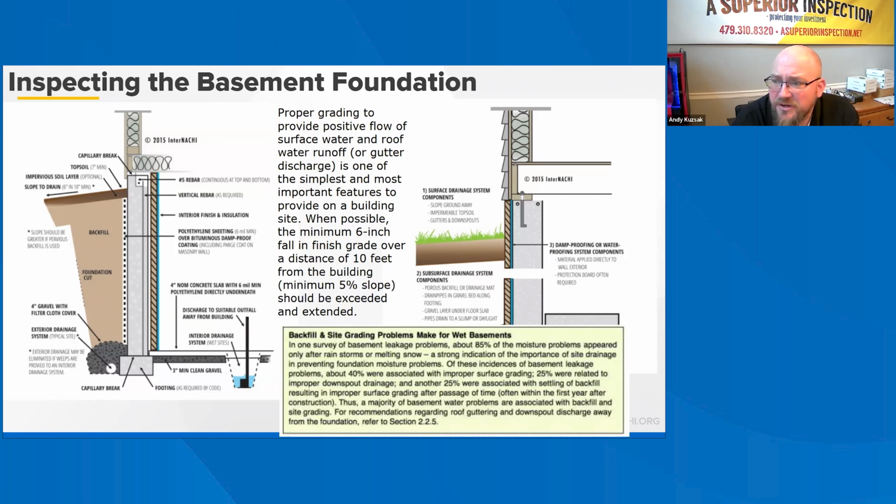Concrete and masonry construction will develop cracks due to shrinkage effects. These cracks widen over time, providing pathways for water intrusion. Controlling these cracks is important, even though cosmetic cracks often do not affect structural integrity. Horizontal reinforcement of the top and bottom of the foundation wall helps control cracking and prevent differential settlement. Epoxy sealant can be injected into cracks in masonry foundation walls to address potential moisture problems.